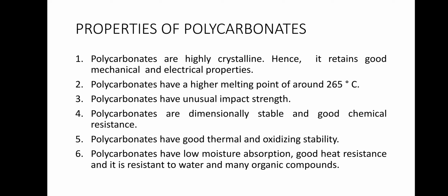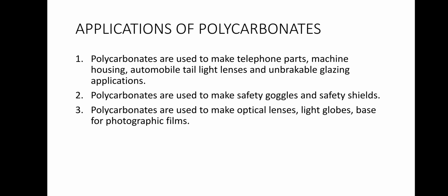Polycarbonates have unusual impact strength, so they have been used to make helmets and other television components. Polycarbonates are dimensionally stable and have good chemical resistance. Polycarbonates have good thermal and oxidizing stability. Polycarbonates have low moisture absorption, good heat resistance, and resistance to water and many organic compounds.